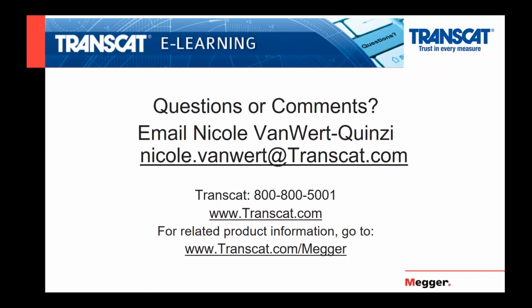The standards IEEE 519 and EN 50160 put limits on the THD, or the total harmonic distortion, and what acceptable values are. So right now we only have recommended limits up to the 50th order, but going forward, especially with the renewable sources, we will see more problems with harmonics higher than the 50th order. And actually the MPQ can do waveform analysis up to the 128th order.